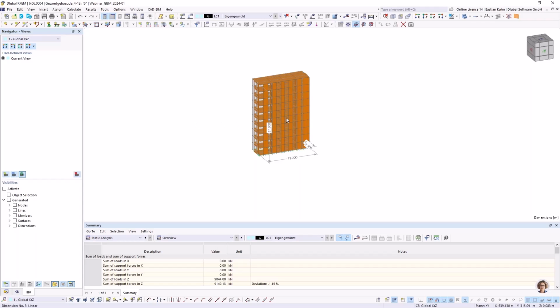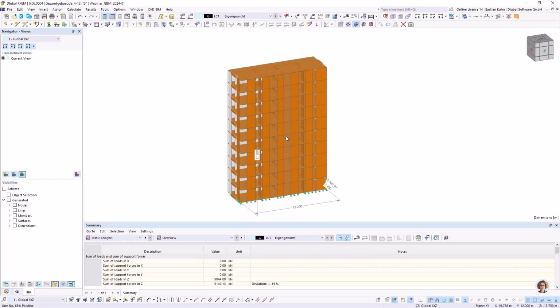And you should not do it, or you should find a way to regard settling of the structure during the assembly. And what is when a stiffening element is failing or whatever. There are hundreds of things you should regard, and when you just calculate the whole building, it can become extremely wrong.